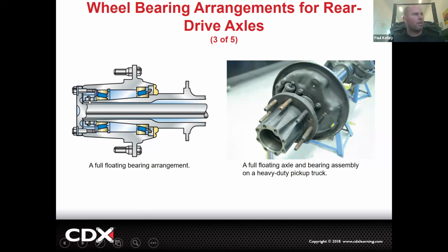And then right here, there's a nut, and that's how you actually adjust this bearing set together. It's almost like wheel bearings we did in brakes. If you tighten it up, it tightens the preload. If you loosen it up, it loosens the preload. But you have to set this one up. You don't just bolt it up and ship it. It's different.